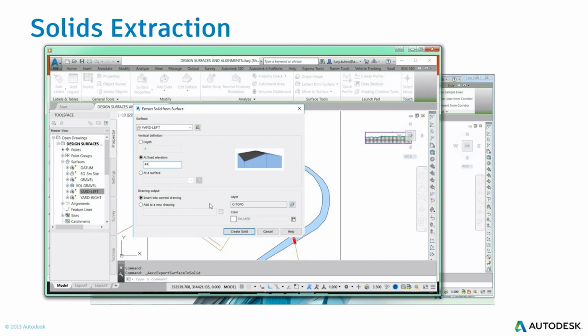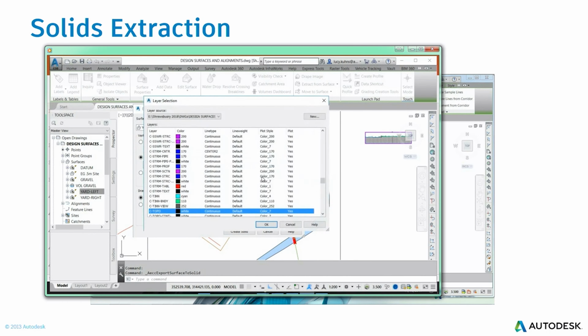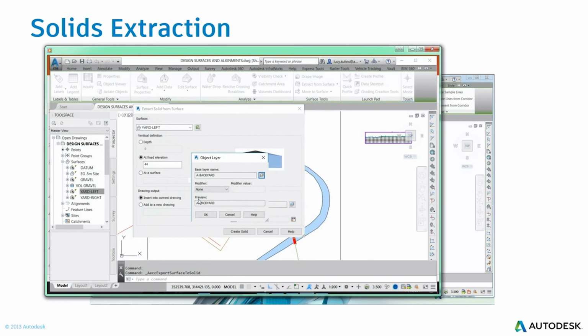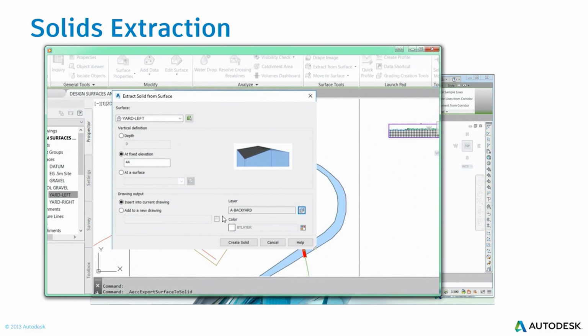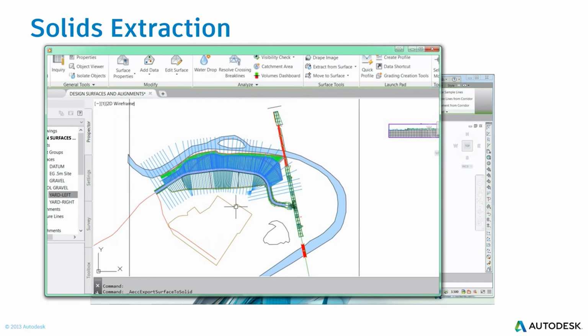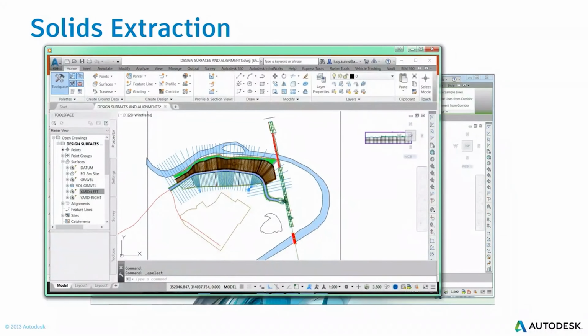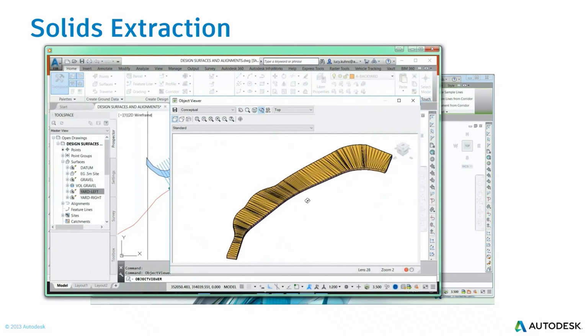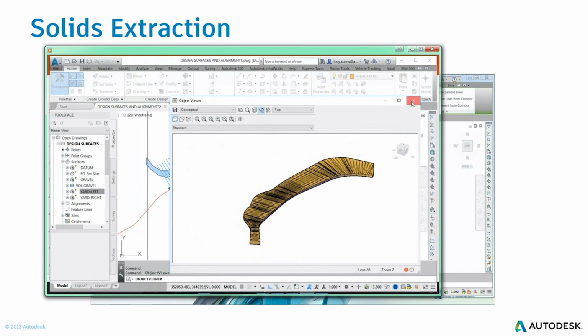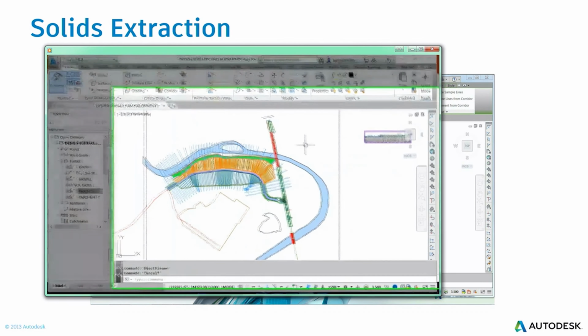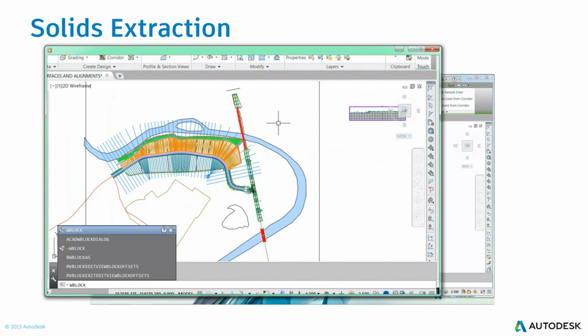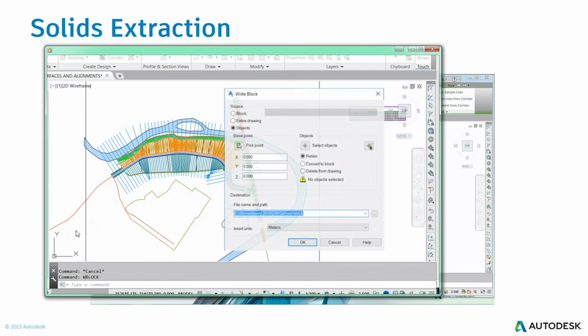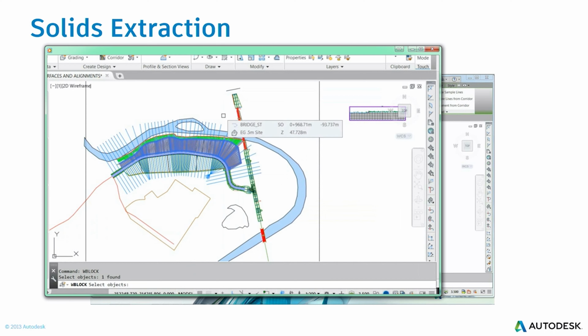It's a very dynamic BIM tool to do not only the roadway but also the grading. When we're dealing with Revit and we do the corridor solids extraction, you must toggle it to take them out as color by layer. If you don't, they're not going to be able to be labeled and attributed adequately in Revit. So that's just a thing to remember. That's something to jot down that's not documented anywhere: you need to do that by layer, not by color. And once we bring this out, here's the trick.